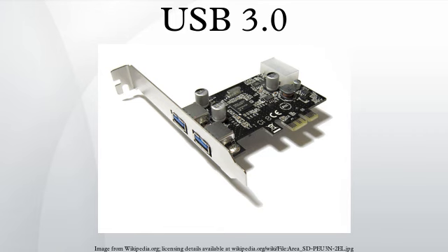Additional power for multiple ports on a laptop PC may be derived in the following ways. Some Express card to USB 3.0 adapters may connect by a cable to an additional USB 2.0 port on the computer, which supplies additional power. The Express card may have a socket for an external power supply. If the external device has an appropriate connector, it can be powered by an external power supply. A USB 3.0 port provided by an Express card to USB 3.0 adapter may be connected to a separately powered USB 3.0 hub, with external devices connected to that USB 3.0 hub.